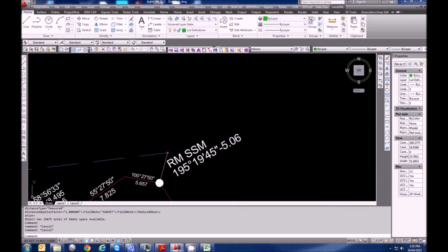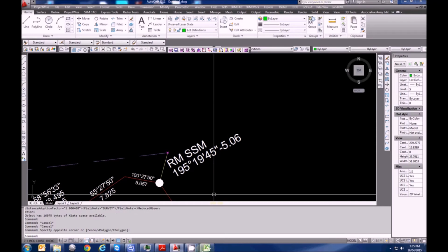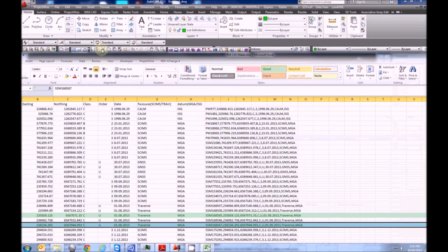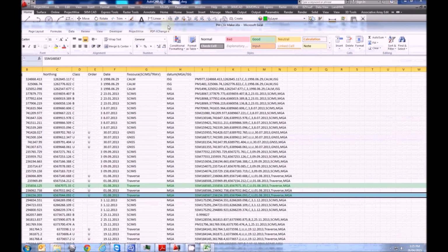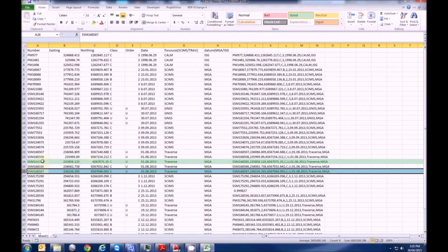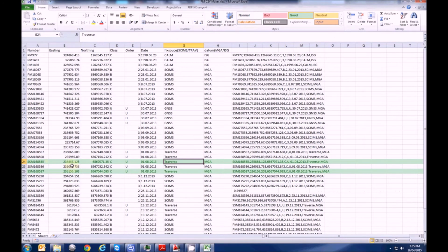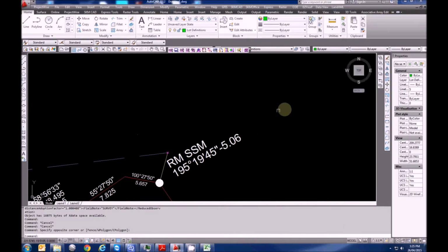Okay, so we're just going to pop those two PMs in. With the package there's an Excel file that has an automatic CSV maker, so this is what I've got. I'm going to bring it over here. I've actually added quite a few now. I've marked the two I want in green. So what you do is you just type in your information, and then right at the end this will concatenate it all into a useful piece for the program. So we'll just pick that up and copy it, and then we come back to our AutoCAD.